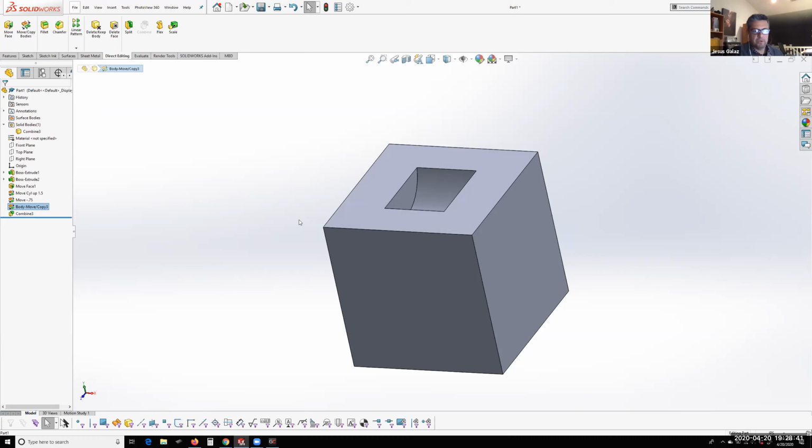But sometimes, where you're in the design phase, all you want to do is just say, okay, I'm going to get this other body and just delete it from the initial body. And sometimes you may also want to pattern something. Maybe you want to pattern this piece, whatever, circular, maybe it's a coin holder or something, right? And this is sized to a quarter, or maybe you want to size another one to a nickel or a penny and so forth. So this might be a faster way to work.